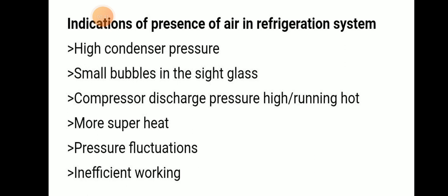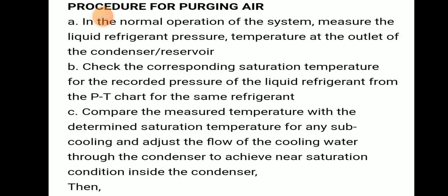High condenser pressure, that means the condenser pressure is high. Small bubbles inside the glass. Compressor discharge pressure is high or running very hot. Then more superheat, pressure fluctuation will be there, and inefficient working. And now the procedure for purging air.